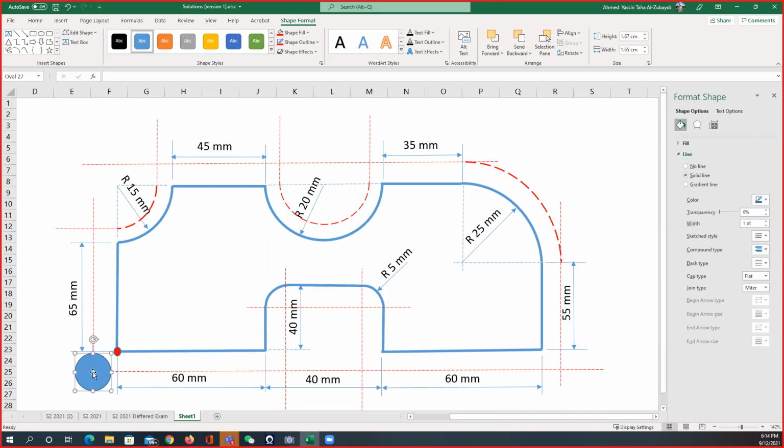It's either going to be made of high-speed steel, very common, but the problem with it is that it cannot work at high speed, and thus is going to take longer machining time, but it's quite cheap. Okay, and the other way is to use a carbide insert. With the carbide insert, I can get a cutting tool with 10 millimeter diameter. Smaller ones tend to be high-speed steel.